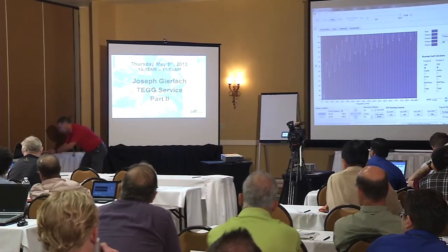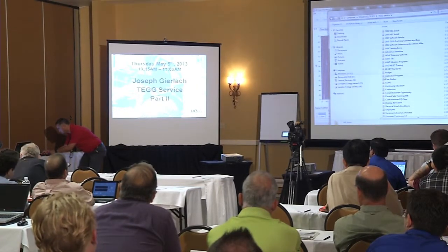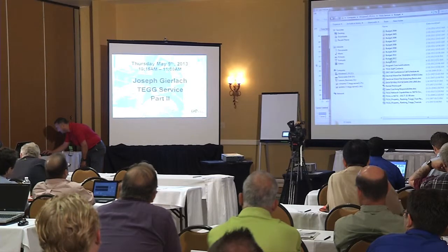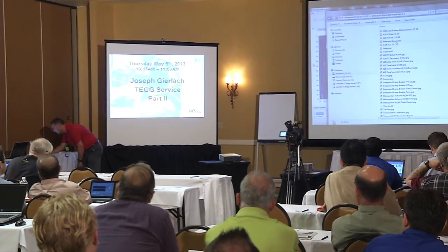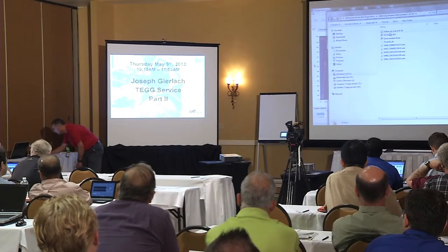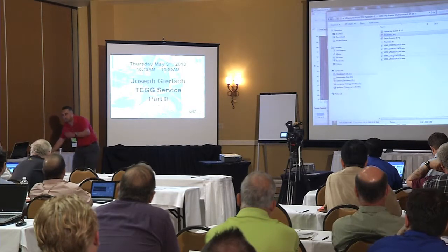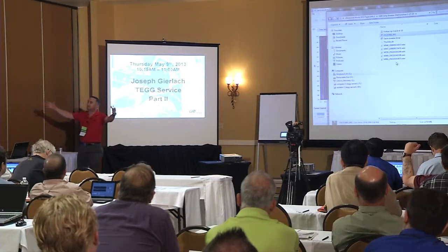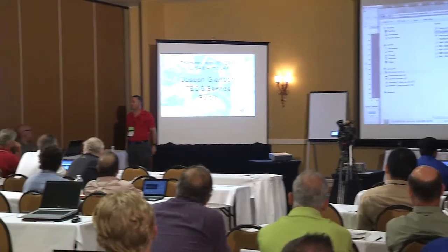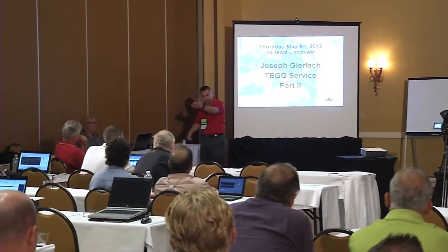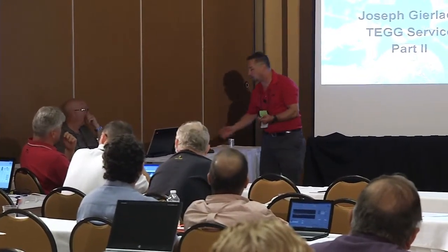I just want to say that another indicator besides the 25 hertz peak is the lack of frequency content. Yeah, I didn't get to that yet. You're right. It looked similar to this. I thought I had a picture of what it would look like, but I guess I don't. It was a unit substation in a packaging container, just a packaged substation, I used to call them. So it was a self-contained 11 kV primary, 400 secondary? 400 secondary, yeah.